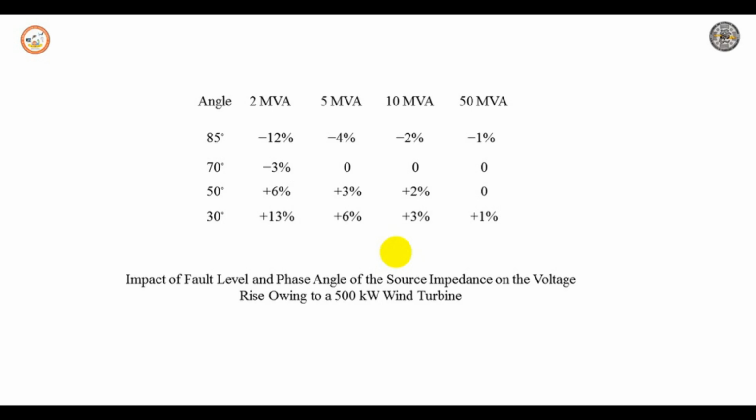The hosting capacity can be as low as 250 kilowatts for a generator connected towards the end of the feeder, but the hosting capacity is strongly dependent on a number of design parameters. When we consider the voltage limit as the biggest influence, using a 110% overvoltage limit instead of 108% will result in a hosting capacity almost equal to 1 megawatt towards the end of this feeder.